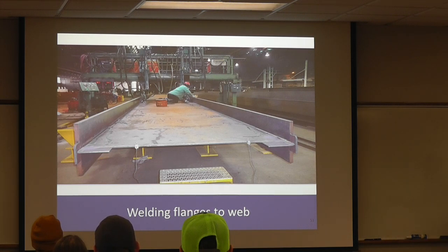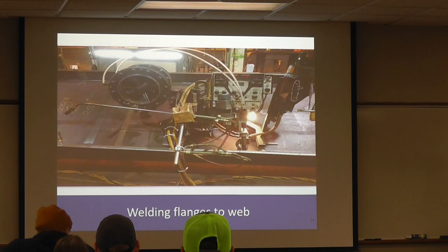They'll support. You can kind of see these yellow beams down here are going to support both the web and these flanges. And the nice thing about laying these on their sides is that, again, we can go with an automated welding process. Have just a nice traveling welder go along and lay that bead of fillet weld for however many thousand feet it needs to go.